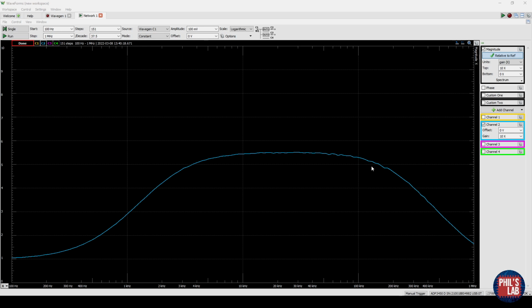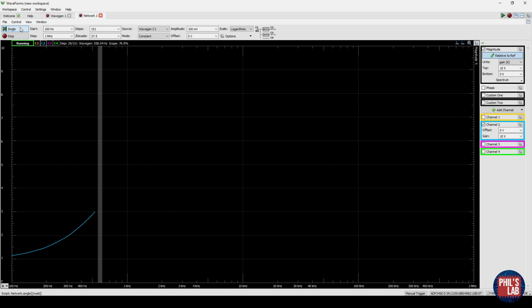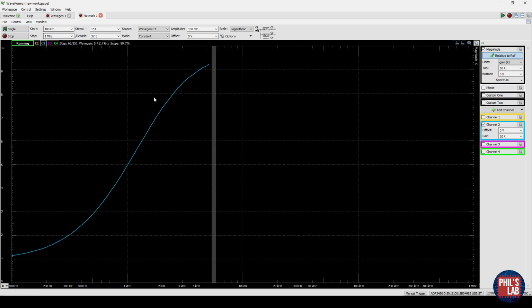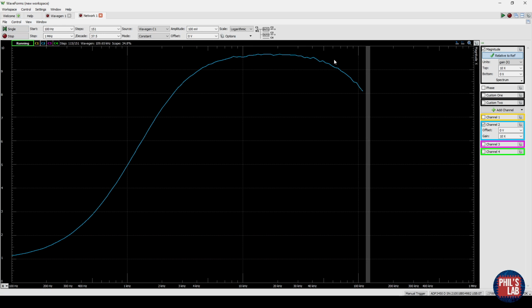By increasing the gain of the closed-loop system, I am sacrificing bandwidth. I can do that even to the extreme by turning the potentiometer all the way to the other side, and I get quite a lot more gain at around 10 linear, but then of course I have a much lower cutoff frequency again, something around 100 kilohertz. This kind of demonstrates the gain bandwidth product.